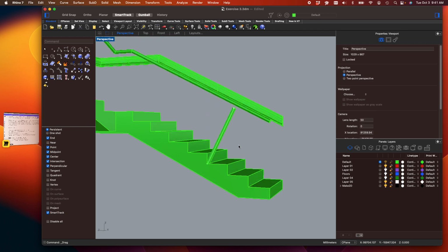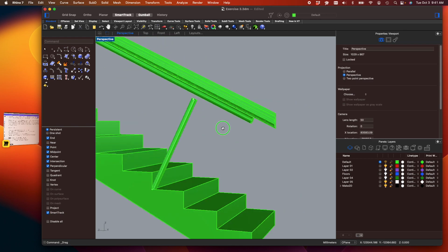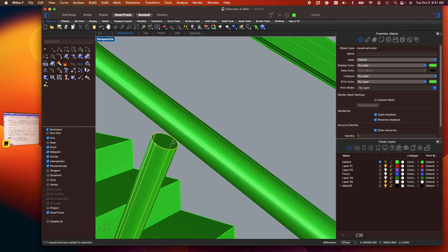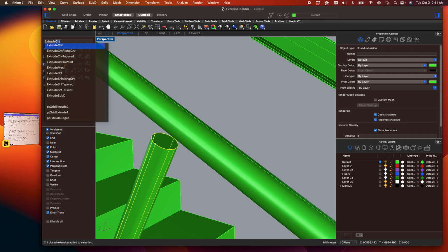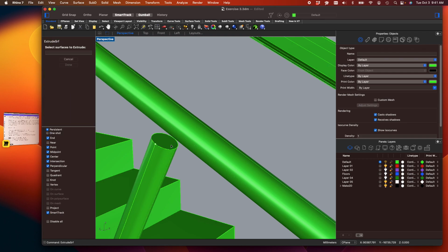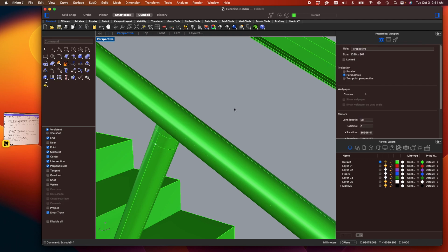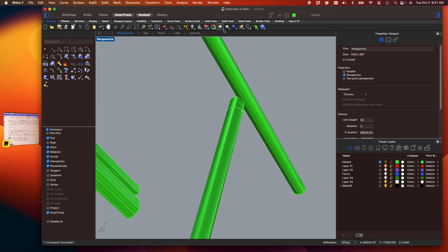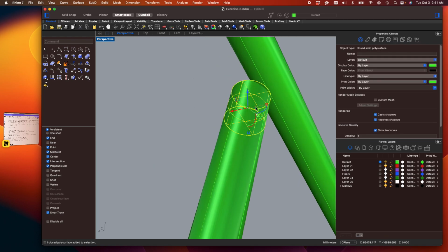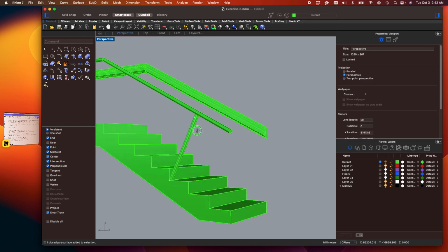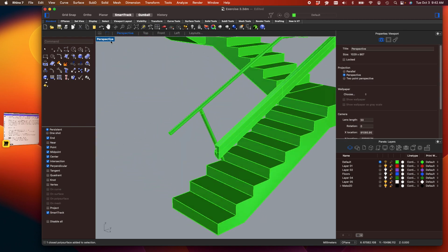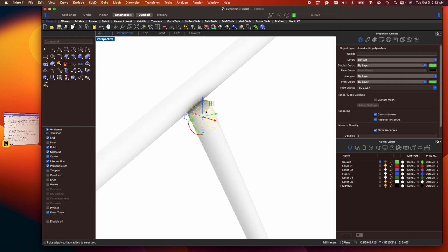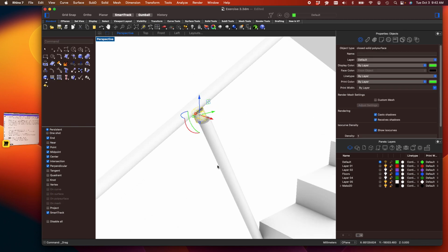Anyway, we still have some time, so maybe I can get into that too. But let's talk about these balusters. It doesn't look like I quite reached it. I could do a couple of things. I can extrude that surface, that circle right there, enter, and just make it a little bit more. That way it at least connects. Close enough, right? I mean, nobody's gonna actually notice that, so let's check it out in render view just to make sure. Ah, man, you're gonna notice. Let's fix it. That's even worse.